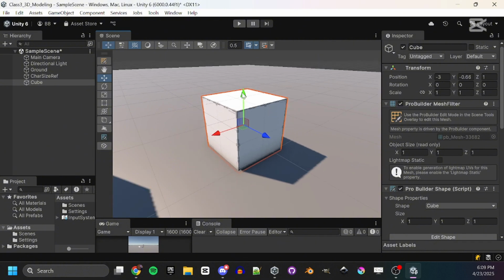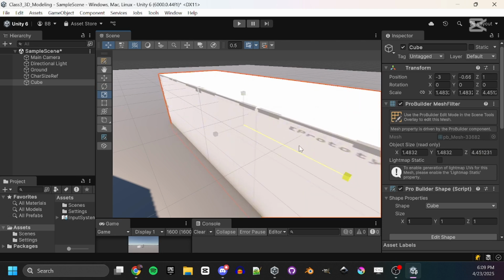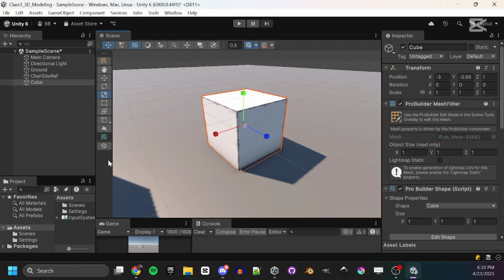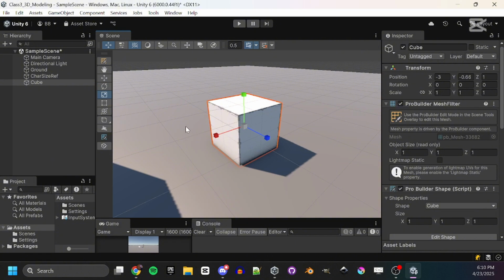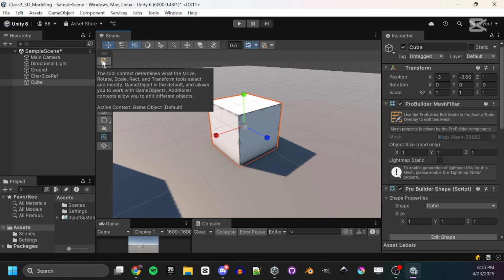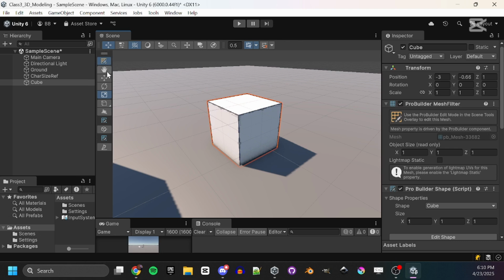With this shape, it works just the same in terms of moving, rotating, and scaling the entire shape. You can scale non-uniformly, and then you can Control Z to get back. But we want to get to the point where we can edit the faces, the edges, and the vertices, because that's how we get into sculpting with 3D. The way we get started is to click this tool here, and then click, let's see, they hid it in one of these things. There it is. All right.